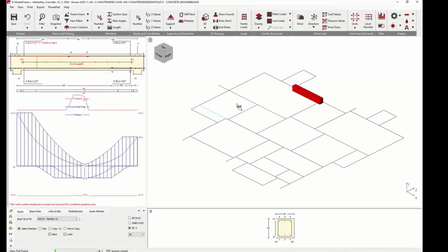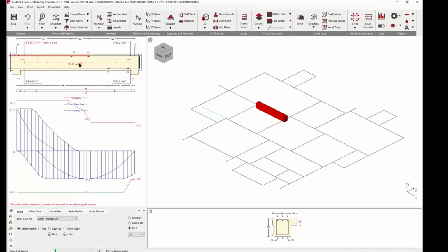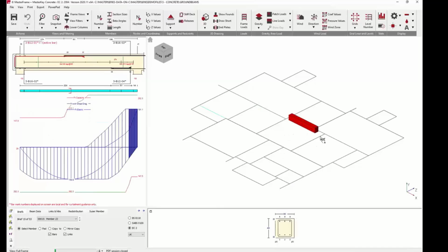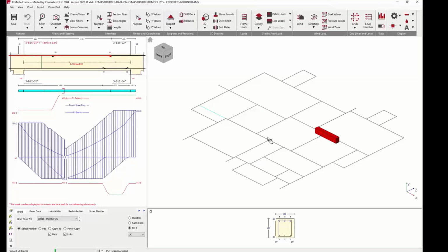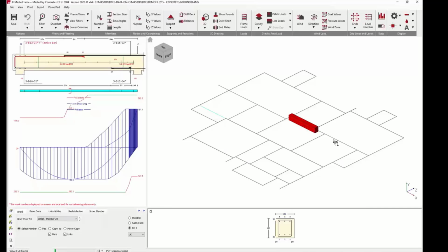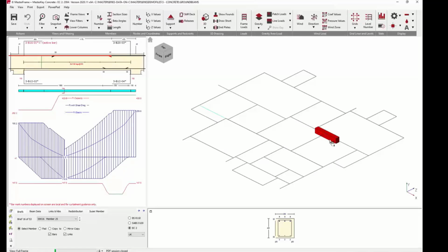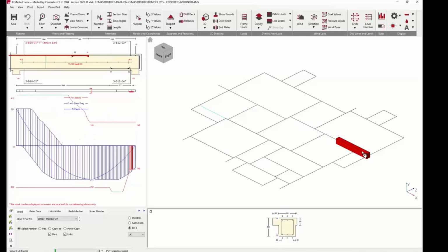And you'll see that, for ground beams particularly, we don't have much in the way of links. 12s at, or sort of 10 2 legs at B8s, so 8mm bars is all you need for those links. And that's very straightforward. Now, stepping back, if I look at this, this is 2.5 meters, and this is a couple of meters, and this is a couple of meters.